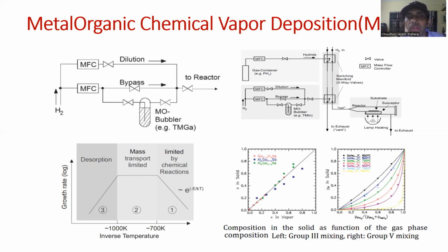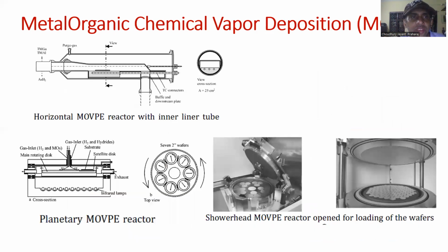And then we grow these different kinds of epitaxial layers by varying these flow rates and varying the different growth conditions. And then we want to, for example, keep dislocation densities low, and we want to get the right material composition and the right dislocation densities in order to get a good solar cell.